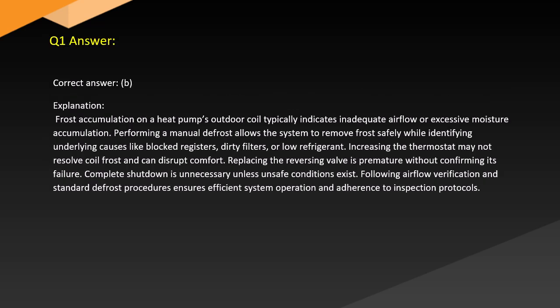Answer. Correct answer: B. Explanation. Frost accumulation on a heat pump's outdoor coil typically indicates inadequate airflow or excessive moisture accumulation. Performing manual defrost allows the system to remove frost safely while identifying underlying causes like blocked registers, dirty filters, or low refrigerant. Increasing the thermostat may not resolve coil frost and can disrupt comfort.